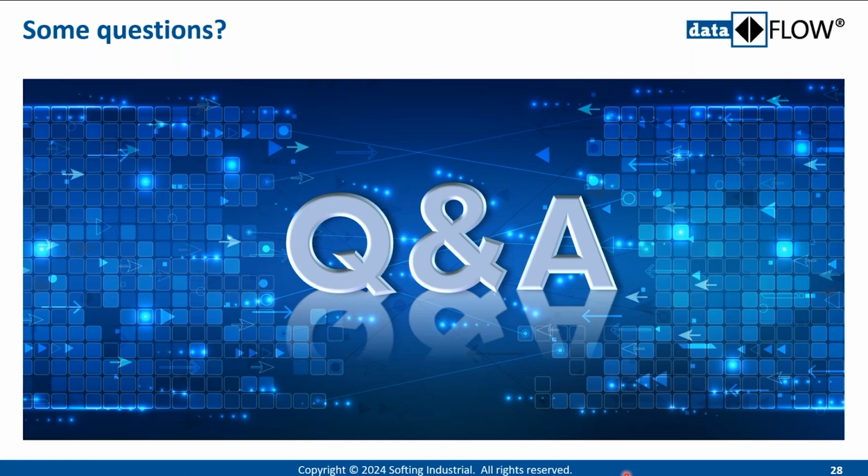We got one from Mohsen Habibi. Is the PA proxy available on the other application layers such as Modbus TCP APL or Ethernet IP APL? It's available on, so this one is, you mean inside the switch? So we have gateway functions in this case, it's Profinet to PA included in the switch.